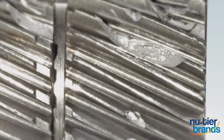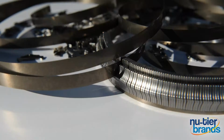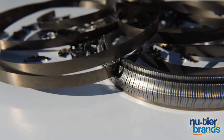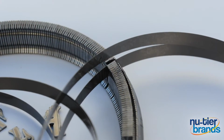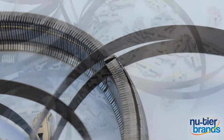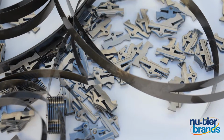Using the wrong type of transmission fluid can cause excessive wear in the belt or chain, pumps, gears, and bearings. At best, you'll risk increased noise, vibration, and harshness. At worst, you can experience slippage in the transmission, and a single slip event can lead to catastrophic failure of the entire transmission and disable the vehicle altogether.